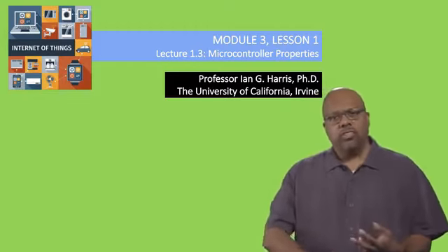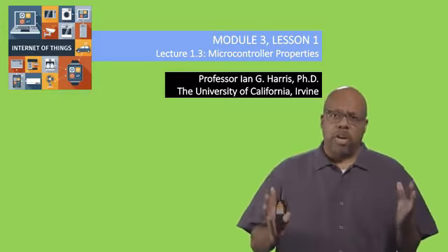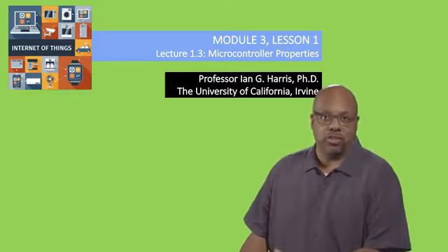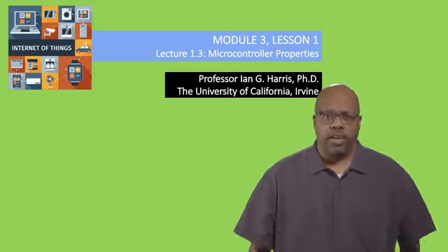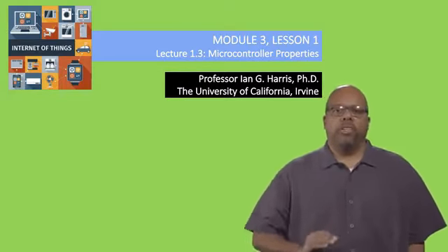So what you need is to have in mind a set of characteristics that your microcontroller needs, sort of the bare minimum from your system, and then you look through the data sheets for the microcontrollers to figure out which one has that, just barely, which is the cheapest one that has that. Now, we're not going to look at a data sheet because those are painful to look at.